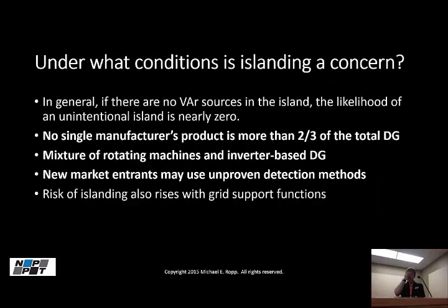When do we and don't we worry about islanding as an issue? I mentioned one case a minute ago that, as we've been discussing, you have to have a match in both real and reactive power in the island in order to have any risk of islanding at all. So the first one we look at is if you don't have a VAR source. If there aren't any capacitors, if there's not something sourcing VARs. Now, remember, this could be underground cable too. But if there's not some capacitive source there, you're not going to get an island.